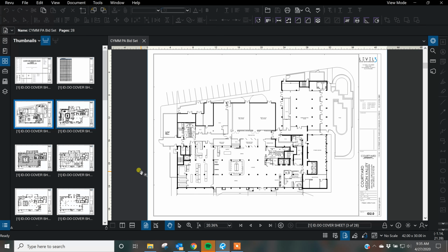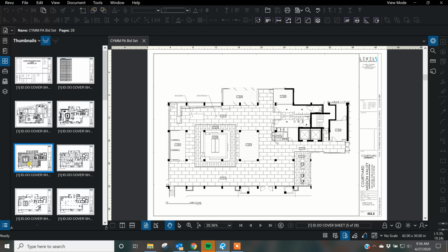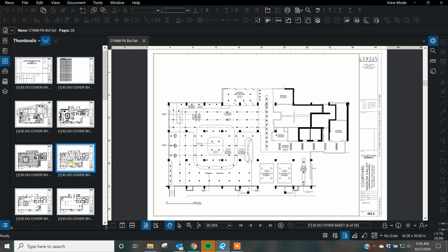This shows the overall first floor plan. We've got our furniture layout for the lobby. This is sort of a zoom in of the lobby. It has all the furniture. It's all tagged with what each item is. Those tag numbers correlate to the spec book. We've got a floor covering plan. This calls out where the carpet, where the tile goes, any notes, flooring pattern directions, tile sizing. We've got a ceiling plan that shows all the can lights, the big decorative fixtures, ceiling heights, ceiling finishes.